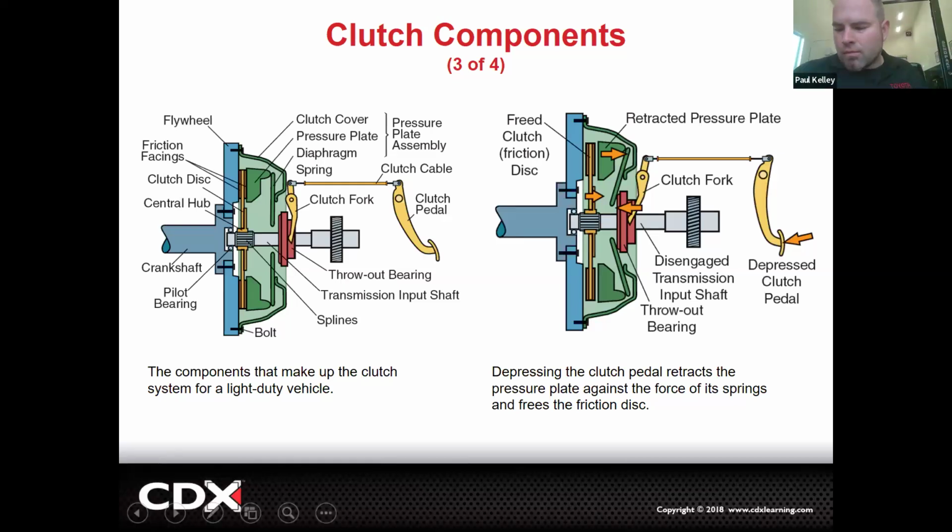There's 3 noises right there. ASE will have a guarantee at least one of those, maybe 2, maybe all 3. All right. And we could diagnose those good enough that I wouldn't necessarily require a teardown. If I were to drive it and just be able to move the pedal and do some different things, I could tell you what bearing it was. The only one I may say to go further is if I diagnose it as a transmission input shaft bearing. I'm going to say, hey, it's the input shaft bearing, but if that bearing's damaged, why it's damaged is a little sketchy.